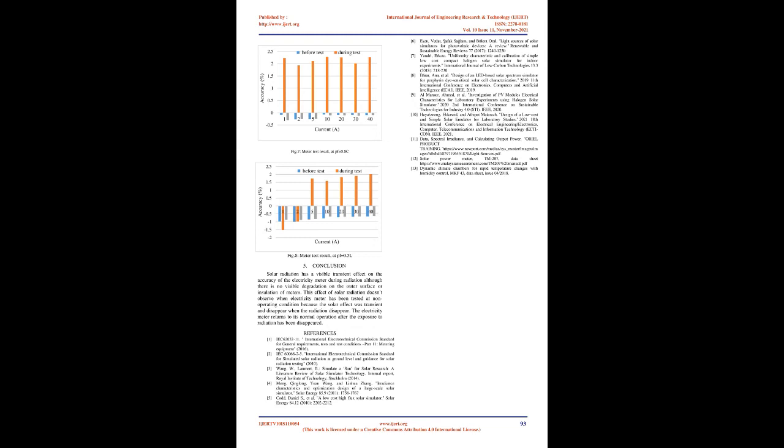For the results, the electricity meter's accuracy was measured by the photo scanning head of the comparator, COM303-3. Table 1 illustrates the average measurement accuracy of the meter at non-operating condition, standard method. First, at room condition, 23 degrees Celsius, in the absence of solar radiation. Second, after 3 days of meter exposure to radiation equal to 1066 W/m2, ambient temperature 55 degrees Celsius. Figures 3, 4, 5 show the accuracy of the electricity meter under different loads for each case.